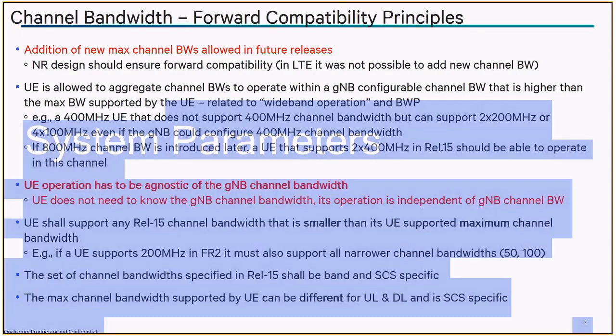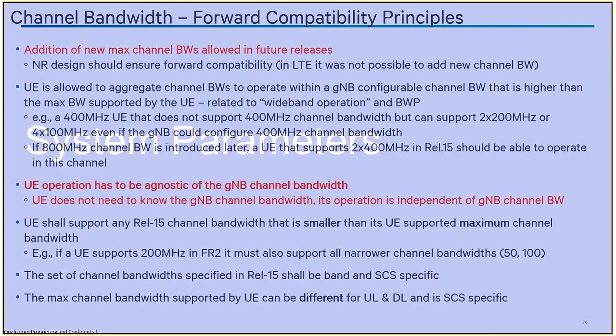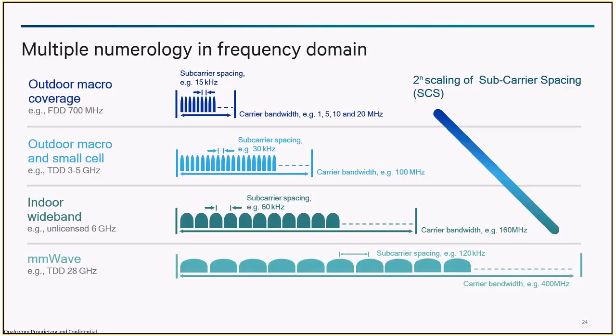The SCS, on an average, the network would not change, but it can send an RRC reconfiguration and move the UE to a different SCS configuration. There would be some guard period. Basically, the RRC reconfiguration would tell in terms of frames, X frames from here, I'm going to shift to a different SCS. Now again, there were restrictions, right? Less than 1 gigahertz, only 15 and 30, then 30 and 60, and then 60, 120, 240. So there are restrictions. It is not that you would see all 6 or 7 in one, it can change. Correct.